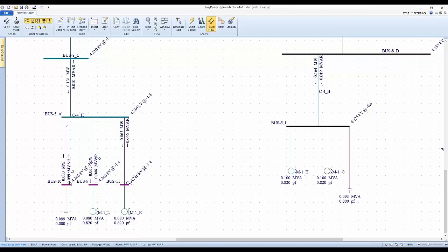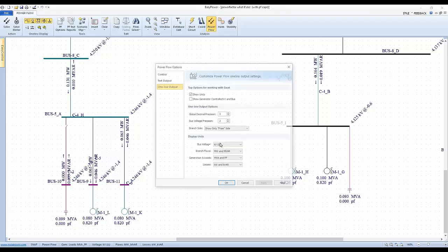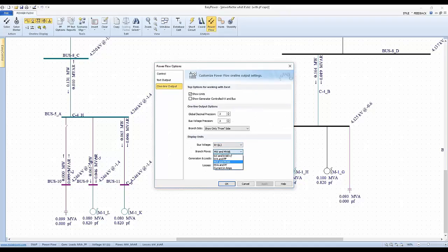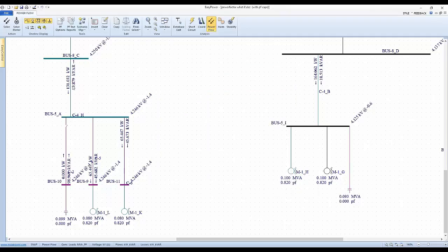All right, so now we can see we have our 99 kVAR capacitive draw, and we reduced our inline. Let's go back and take these back to kVAR. We've reduced our inline draw upstream to just under 10 kVAR versus the 100 that we were seeing before we had the capacitors in there.